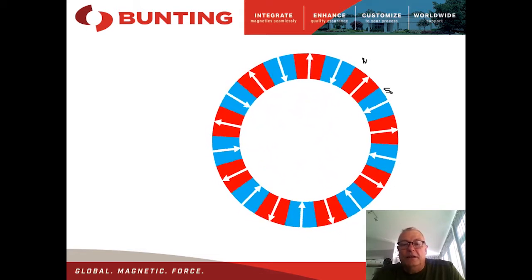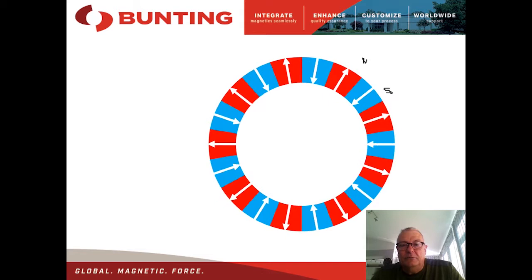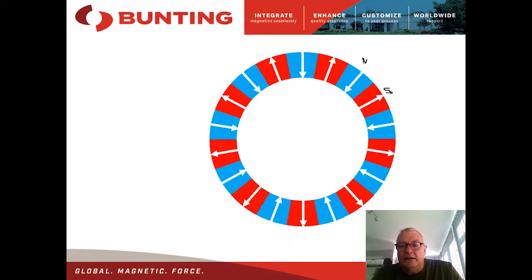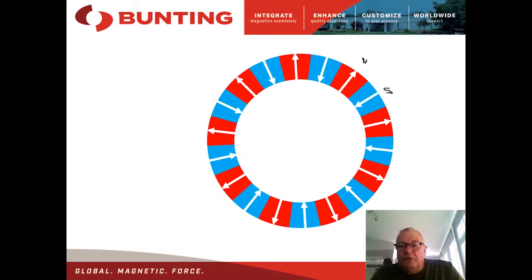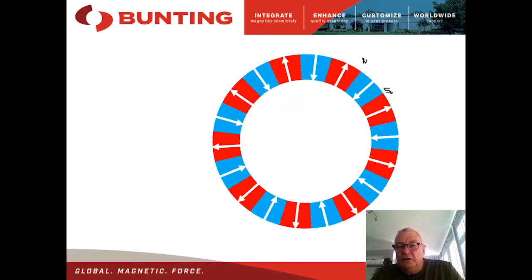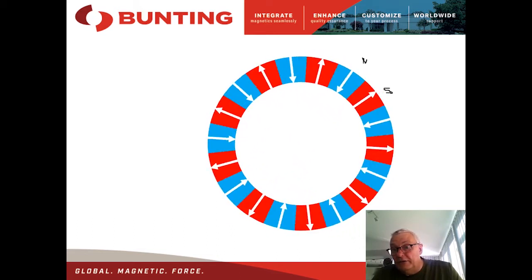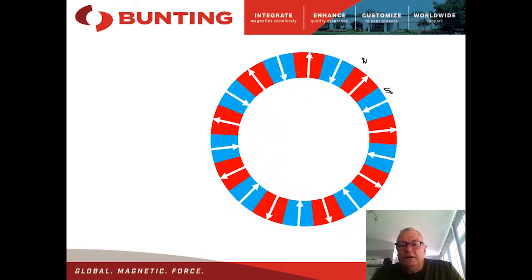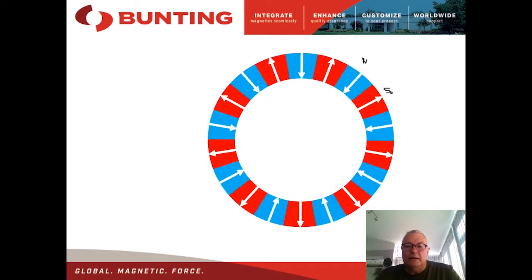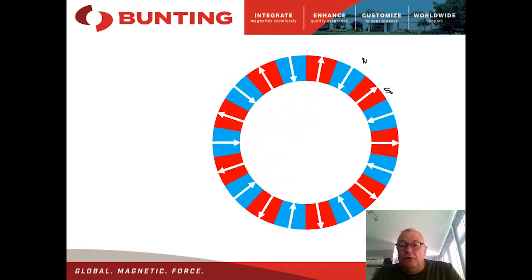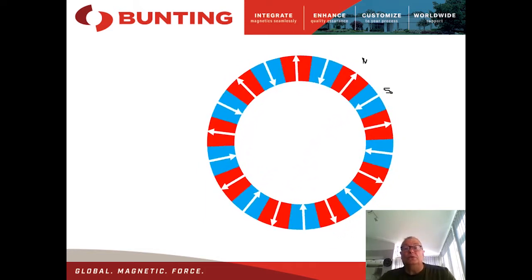So the eddy current separator is merely a method of inducing an eddy current force in a conductive material. Before 40 years ago, in the advent of neodymium boron iron permanent magnets, which are very strong, this would have been done by changing electrical current in something like a linear motor for a railway or something like that.